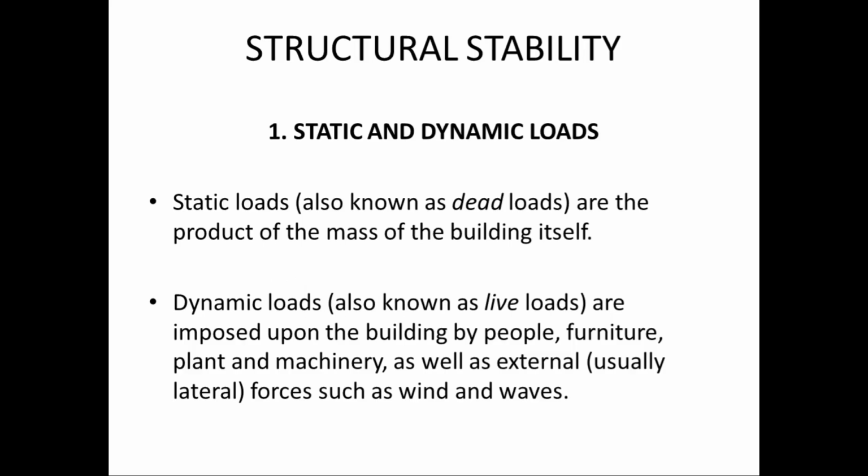To get on to structural stability, structural engineers talk about the difference between static and dynamic loads. There are lots of terms that you'll probably come across for this. Static loads are known as dead loads, dynamic loads are known as live loads, and you probably will hear other terms. The fundamental difference is, of course, the static loads or the dead loads are the mass of the building itself. All the materials that go to make that building are the dead loads of the building. The live loads of the building are anything over and above that, loads that are imposed upon the building.